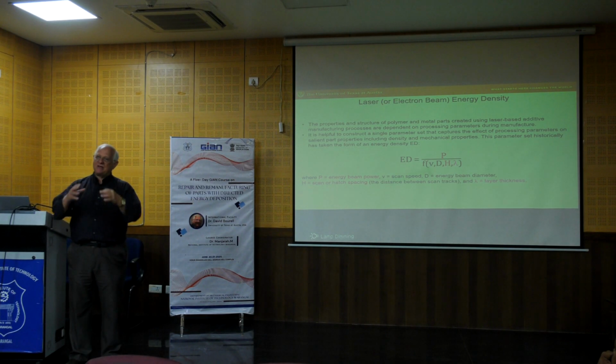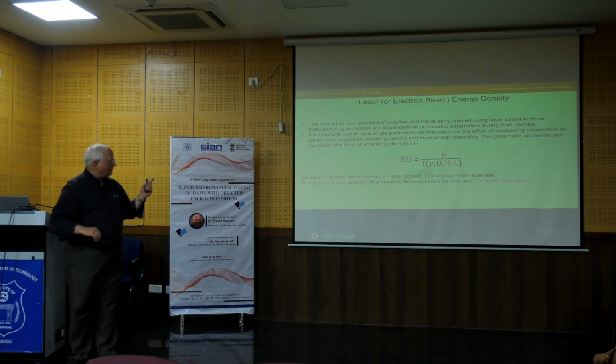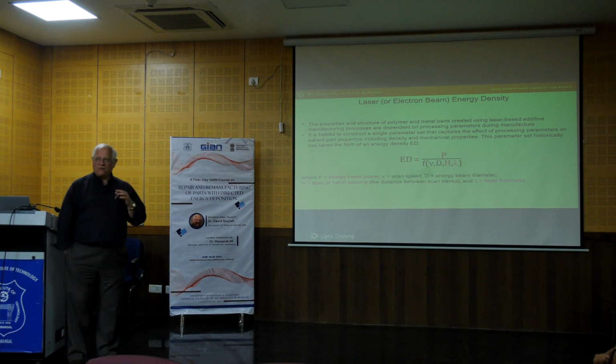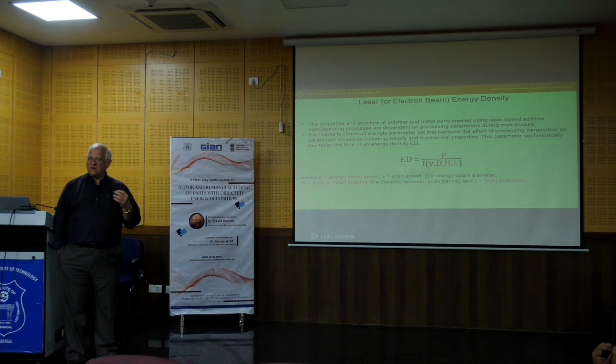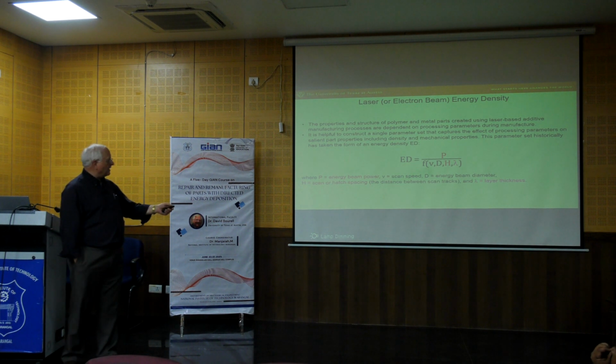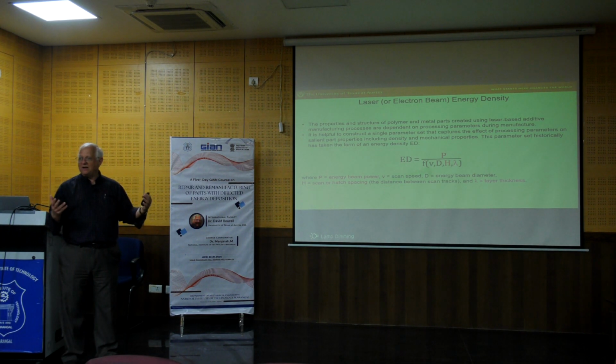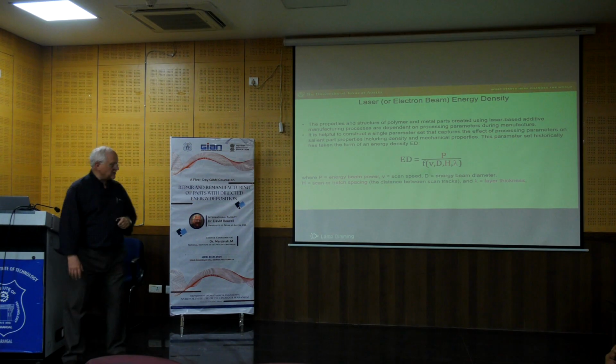Presumably, if I have an energy density value that works for good mechanical properties, say, or high strength in the part, if I can establish the critical energy density, then I have the ability within limits to change these around as long as I keep the same overall value for the energy density.